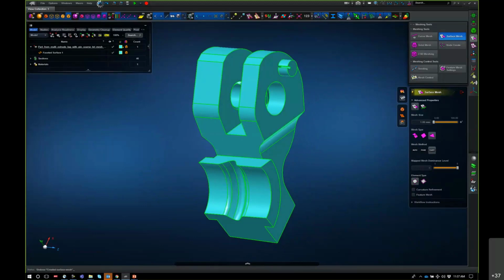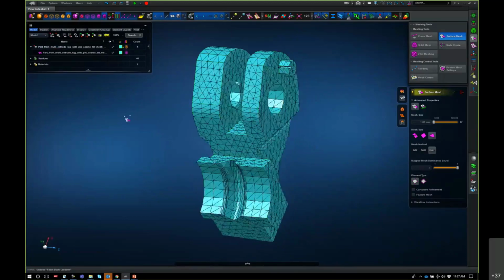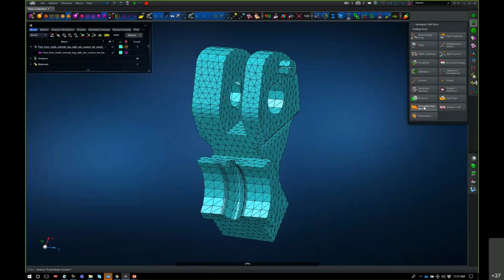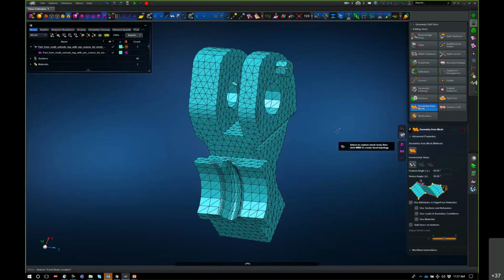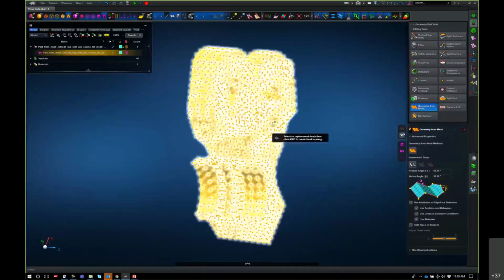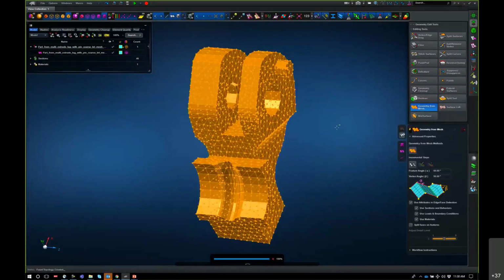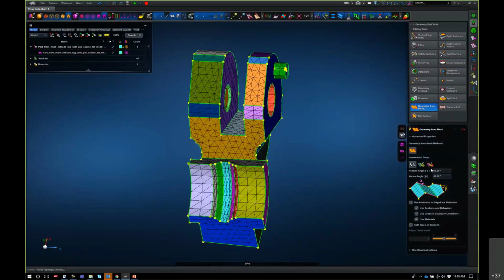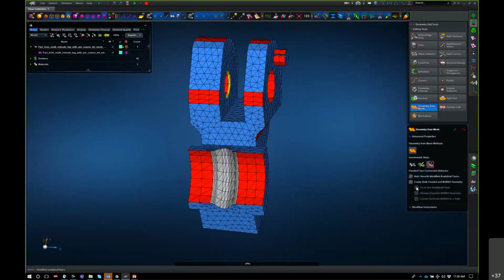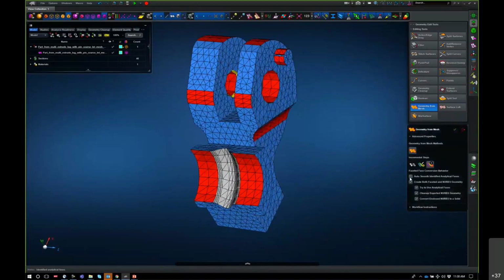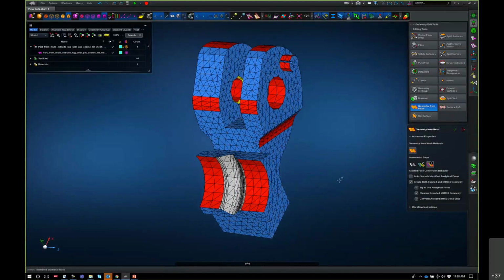I'll go all the way back now. Let's talk about facet bodies or NURBS geometry. So NURBS, which is a really exciting part here, has so many cool potentials. Same process before. There's the same topology I had. This time, I'm going to create the NURBS. I still have to create facet bodies, but I don't have to smooth it. I don't care about the facet body. I'm probably going to delete it when I'm done. So I can turn that off. The smoothing just saves a little bit of time. And I have all the other settings that, generally speaking, should be on by default.